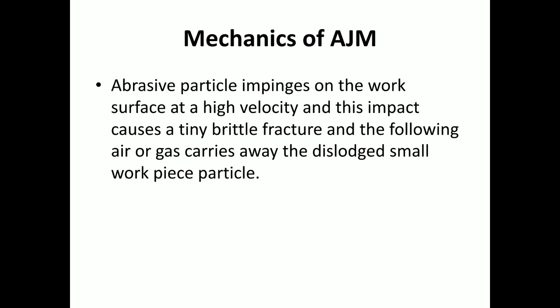Abrasive particles impinge on the work surface at a high velocity, and this impact causes tiny brittle fractures, and the following air or gas carries away the dislodged small workpiece particles. Means these high velocity particles, when impinging on the surface, create tiny brittle fractures, and the gas coming just after takes away the removed particles from the place, so that the next particle can hit and create a cavity.